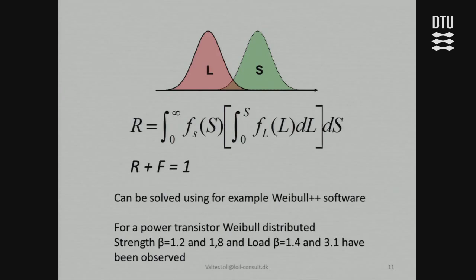A.D.S. Carter, which is a basic book on this theory, describes two cases where all real design will be somewhere in between. And besides the safety margin, he defined something he called load roughness, which is the standard deviation of the load divided by the combined standard deviations.